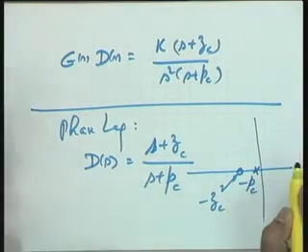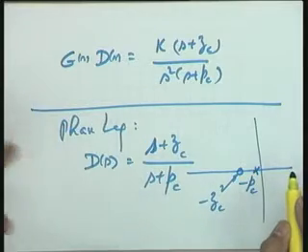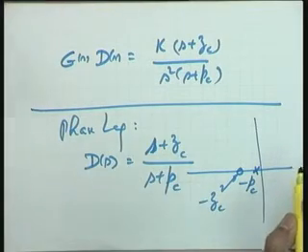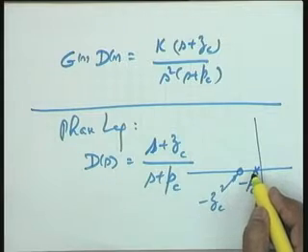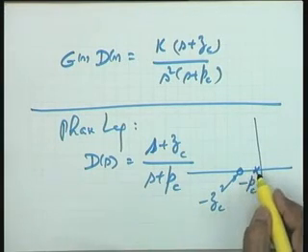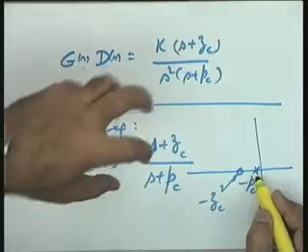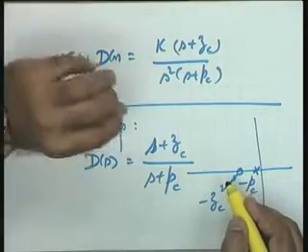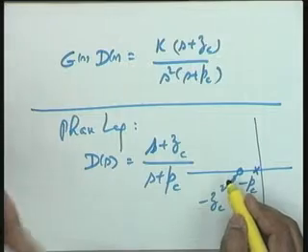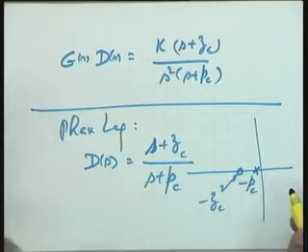As you will see, the reasons will become clear. Why do we take it close to the pole? One of the qualitative reasons I gave you is that this particular pole is going to destabilize the system, is going to deteriorate the stability of the system. The effect on stability will be compensated if there is a zero close by. This is a qualitative statement. Quantitatively this will become very clear when we just now take up an example.